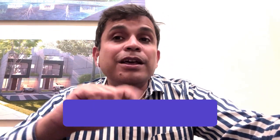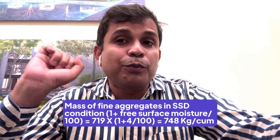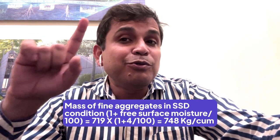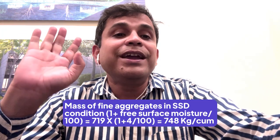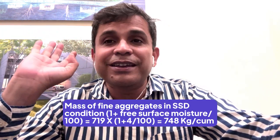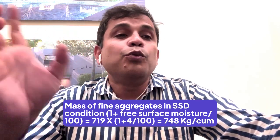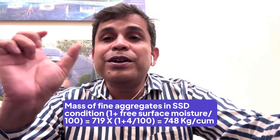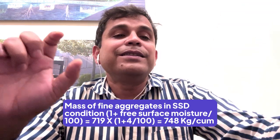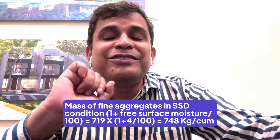Because the moisture is there, the 4%. So 1 plus 4%, that is 1.04. That will be 719 into 1 plus 4 percent, which becomes 748 kgs. Yes, it's coming 748 kgs. So if we are taking 748 kgs, we are getting 719 kgs of sand, and 748 minus 719 is around 29 kgs, 29 kgs of water.